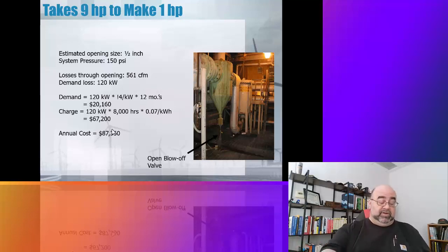Then I go into, and I recommend you enjoy reading it, the air leaks at the fungi and cooking plant. First air leak, we identified a single air leak at the bottom end of one of the fungi tanks, a 1/4 inch opening. Using the leak formula, that leak put out 140 CFM, resulting in a 30 kilowatt demand. That one leak, a little hole basically, was a $13,000 per year hole. The second one was actually that one.